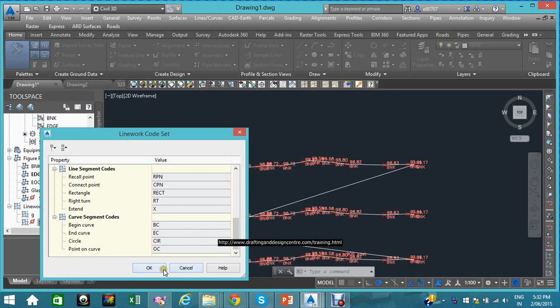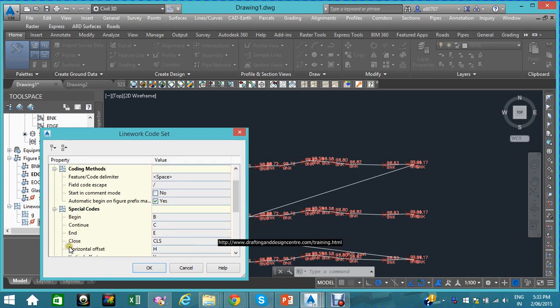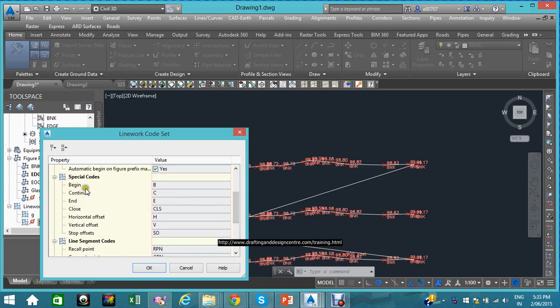Curve segment is here. Once you follow this special code, when you survey using Topcon, you can use Trimble Link to import the CSV file. And then once you import it, you can either set the database using this B and C by changing the CSV file, or, because sometimes it's very hard to change the CSV file, the right practice would be that the surveyor, when he or she is in the field, should follow this special coding.